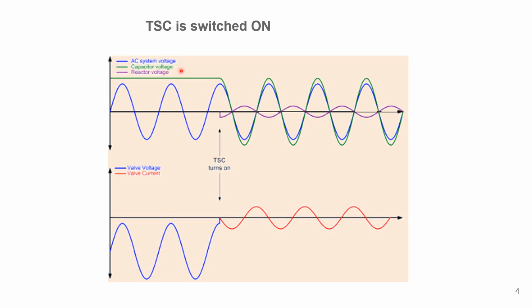Case 2 is when the capacitor voltage is equal to the supply voltage when the thyristors are fired. The analysis shows the current will jump immediately to the steady state value. The steady state condition is reached in an infinitely short time, and the magnitude does not exceed the steady state value, but thyristors have a limit.